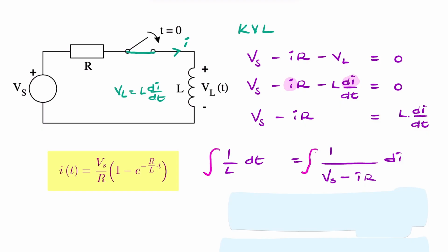So we put in an integration sign on both sides of this expression. So we're integrating here over time. So I'll integrate from t equals 0, that's the instant that the switch was closed, until some arbitrary instant t. And the current initially will be 0. The initial current will be 0 because it's an open circuit and there's no residual current in the inductor, and as I said, initially the inductor acts as an open circuit. And then I'll just put I here.